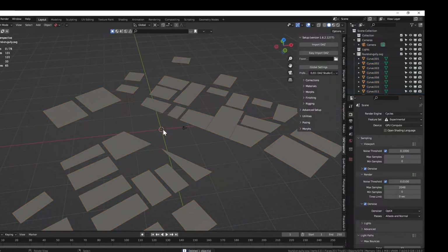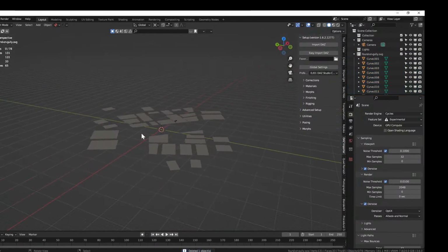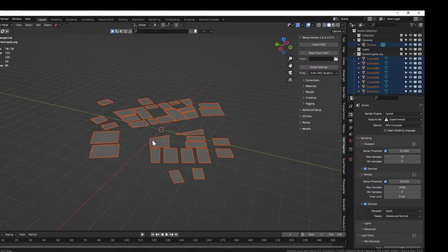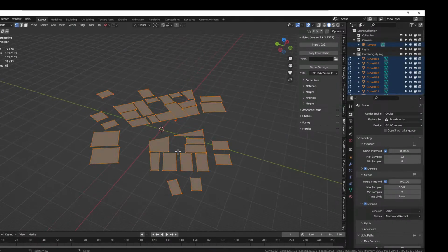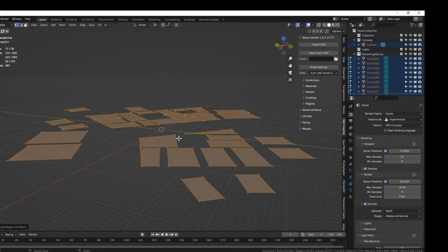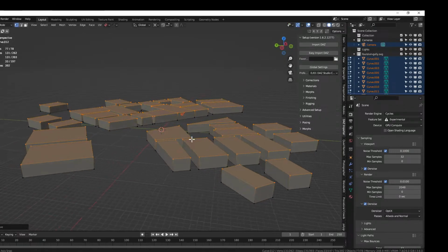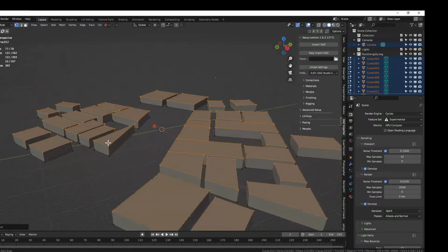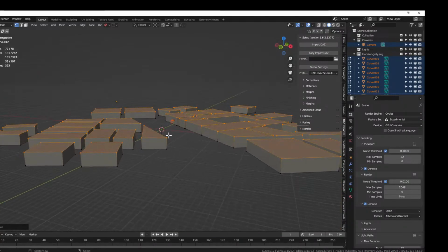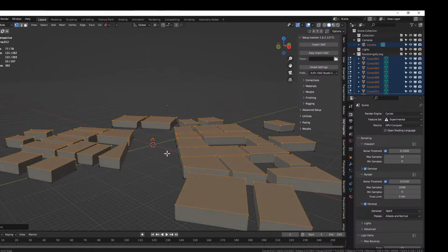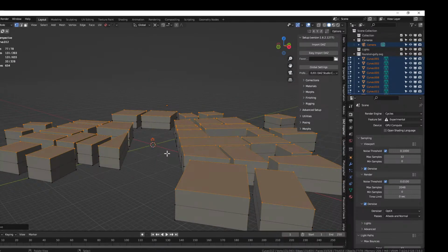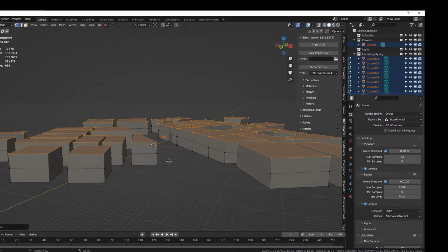Now I'm going to get rid of my cube again. A, tab. Now E, GZ3. First floor. Now, I think every one of my buildings is going to have at least 2 floors because the first floor is that structural level. But E, GZ3, 2 floors. These are also small floors. 10 feet is not a huge floor. So you could make it a bit bigger, but I think it works for what I'm doing here.